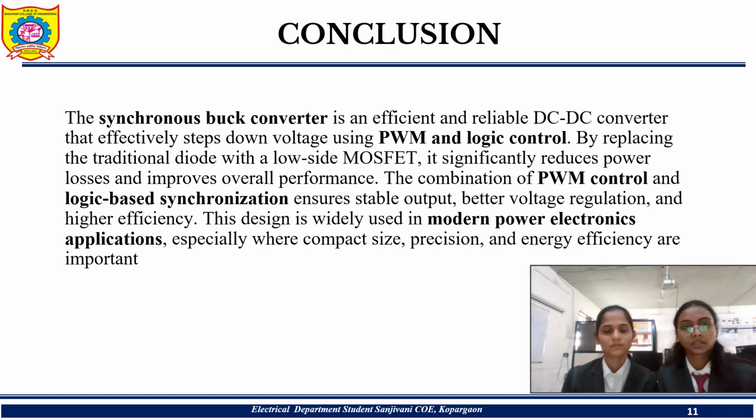And conclusion: the synchronous buck converter is a DC to DC converter that steps voltage from higher to lower by replacing the traditional diode with a low side MOSFET. It significantly reduces power losses and improves overall performance.